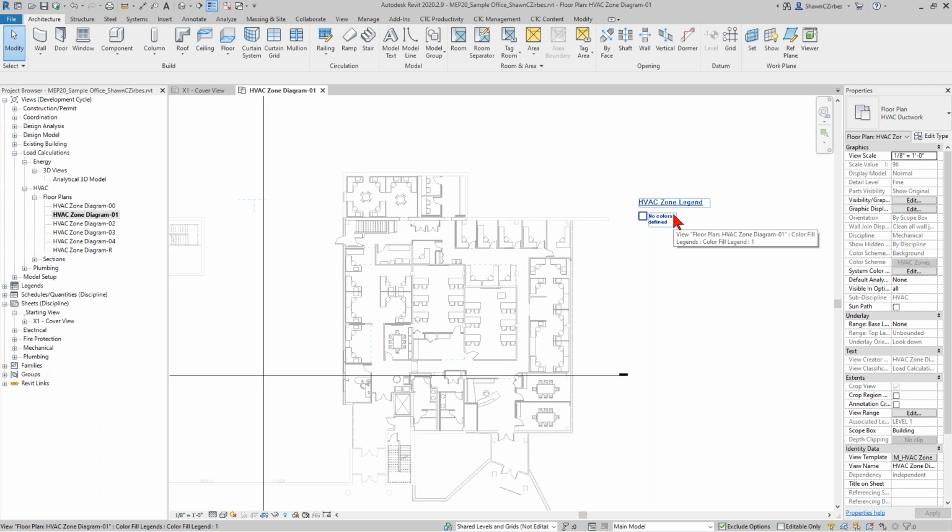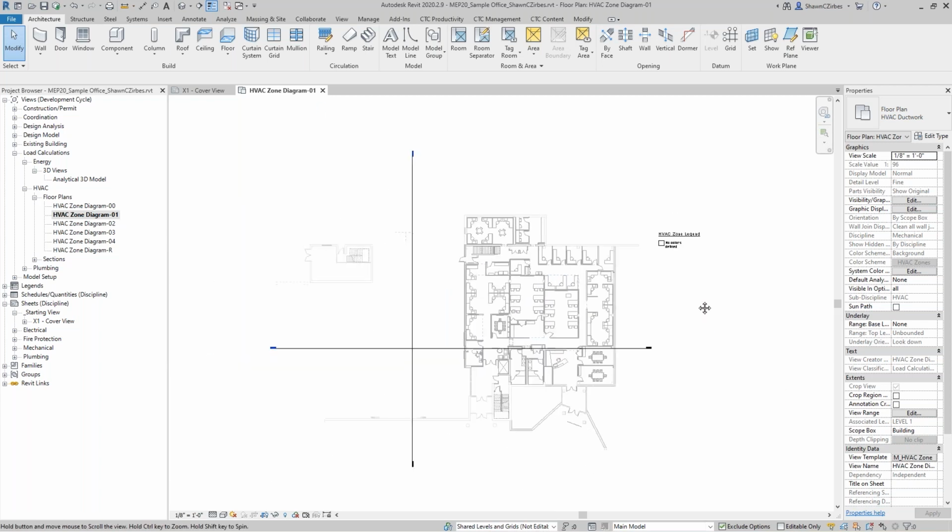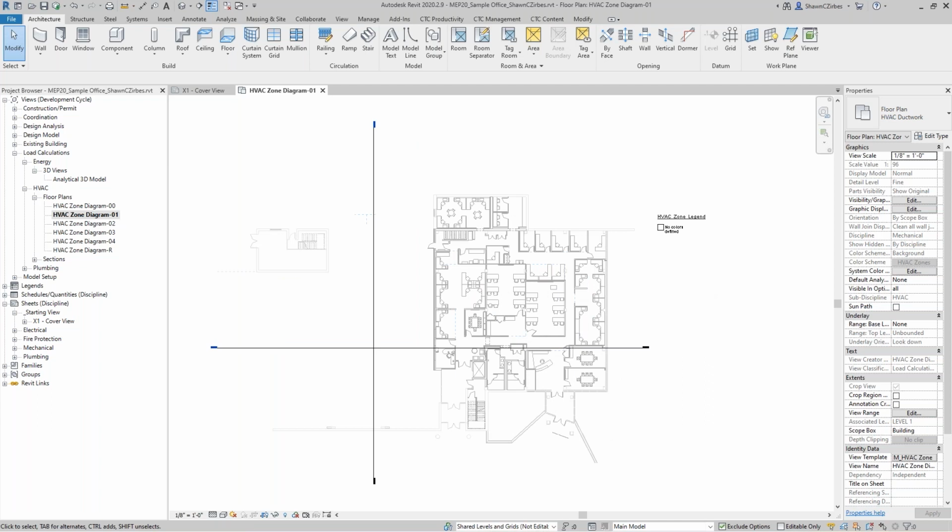So when I reloaded the architect's background and set all my information up here and got my scope box all configured for my building, it actually automatically updated this particular view. There was no work for me to do at all. It's already all set up. And the view template here is already queued for everything that I'm about to do here with spaces.